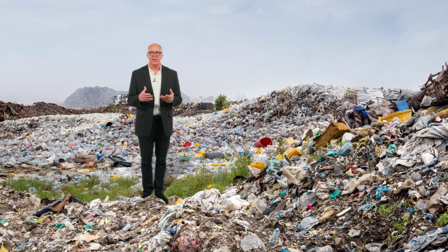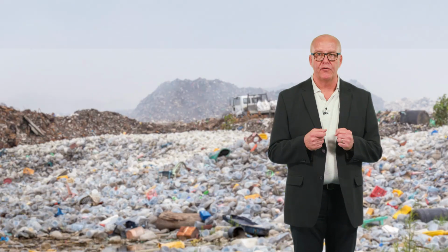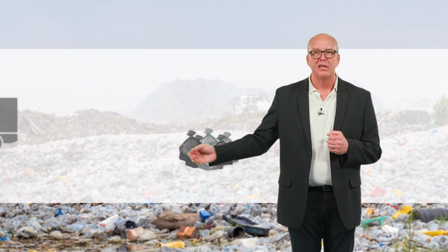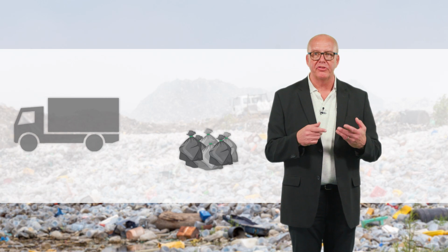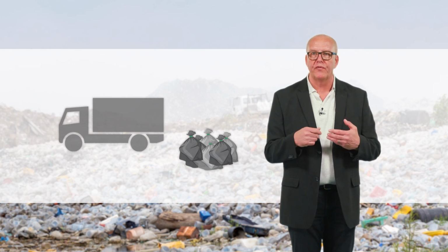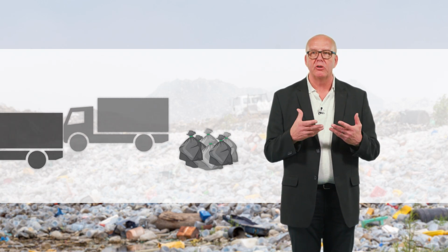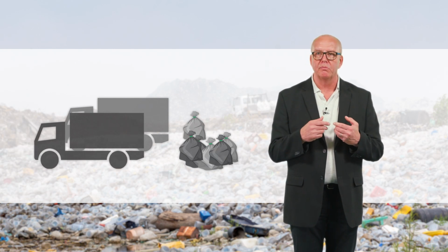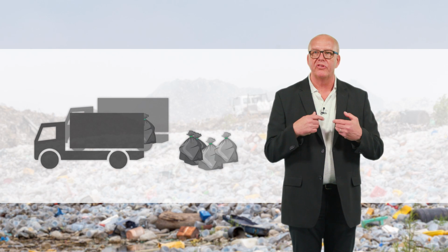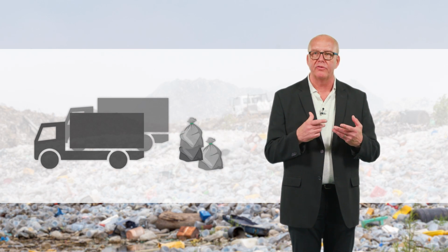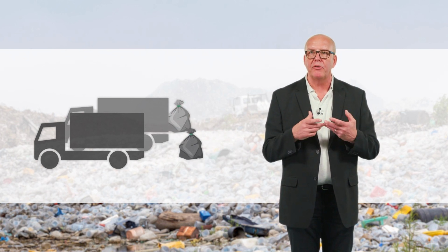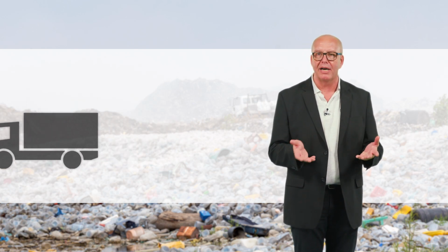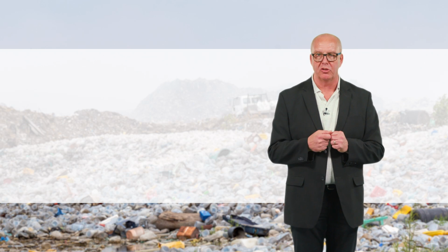In general, there are 2 closure methods. The first one involves securing waste ex situ. In this case, waste and contaminated soil is removed from the site. It is relocated to an appropriate landfill. This method is suitable for small dump sites, with a volume of maximum 5,000 cubic meters. It is a very fast and cost-efficient closure method, and the site is cleaned up after waste relocation.